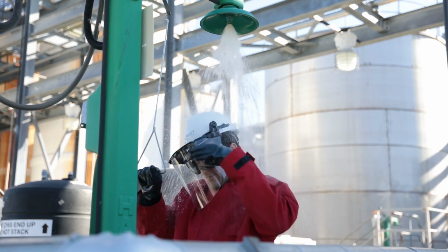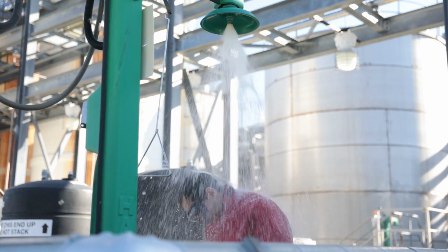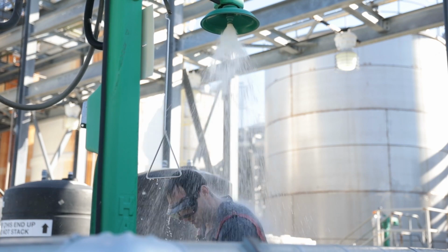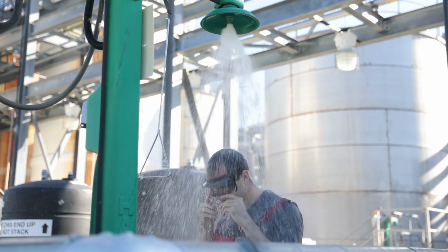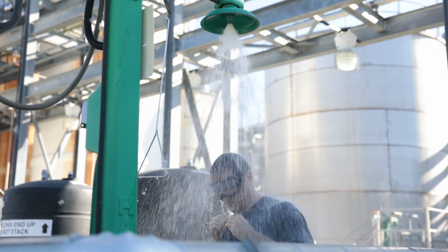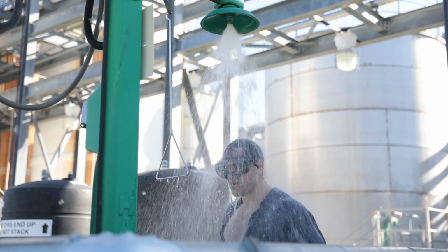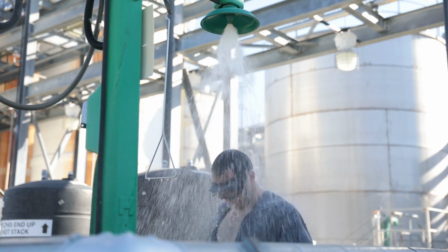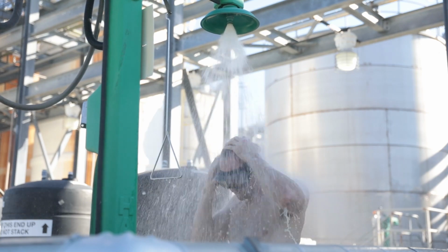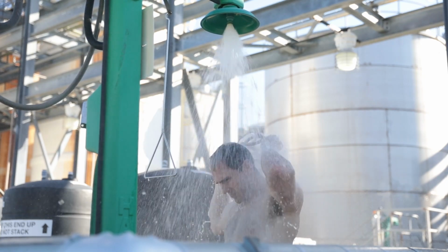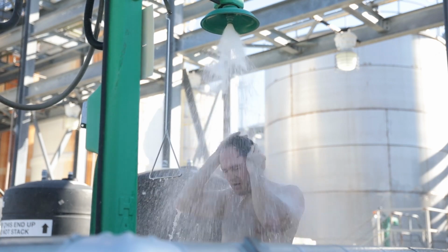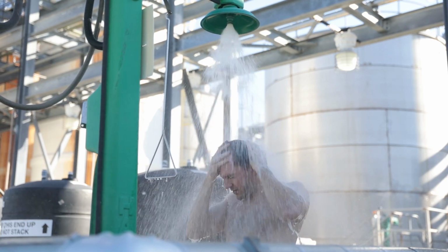If your skin, hair, or clothing is exposed to caustic, quickly get to a safety shower. Keep goggles on and hold them tightly to your face unless the eyes have also been exposed. Goggles prevent caustic on the hair from washing into the eyes. Remove clothing as soon as possible while showering. Forget modesty. You must remove contaminated clothing to prevent injury. After washing your hair, face, and hands, remove the goggles. Continue showering for at least 15 minutes or as specified in the SDS.